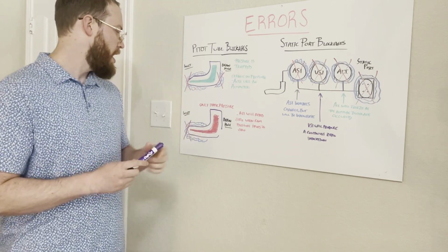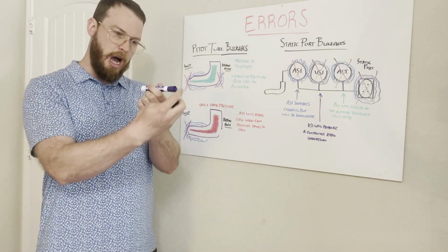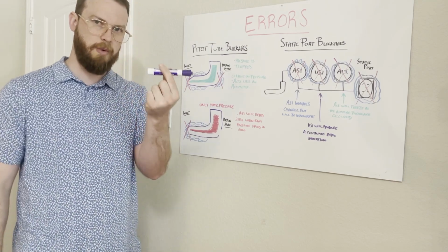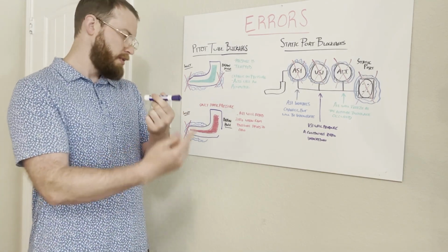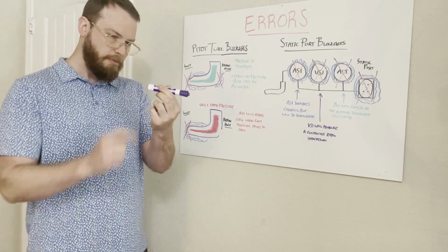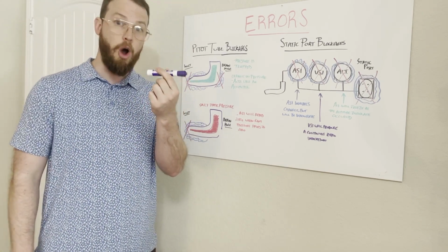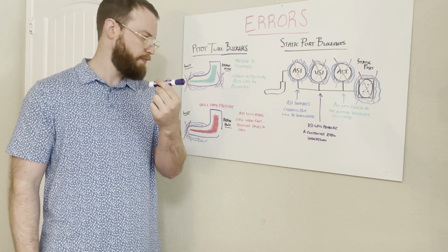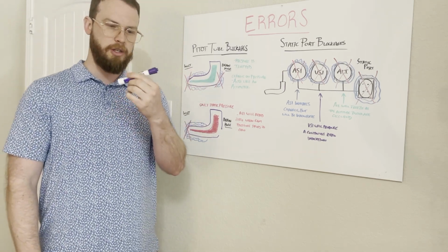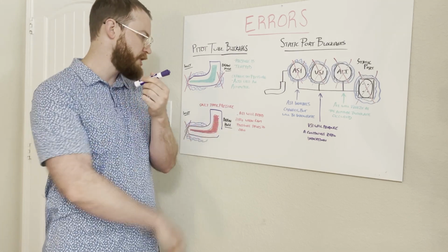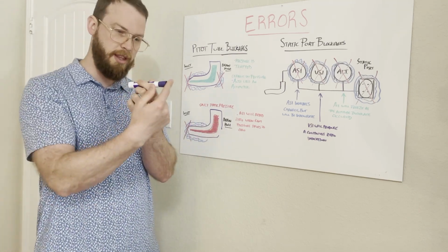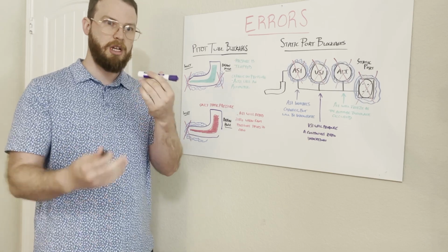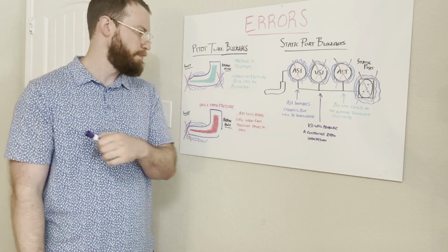Okay. Now let's talk about if only our ram air is blocked. So here's just the cap on this side here for our ram air. That's blocked for ice or whatever reason, but our drain hole is open still. We're only going to receive a static pressure reading. So that's basically going to give us an airspeed indication reading of 0 when the ram air indications drop to 0. So it's going to steadily drop to 0 and then stay there.